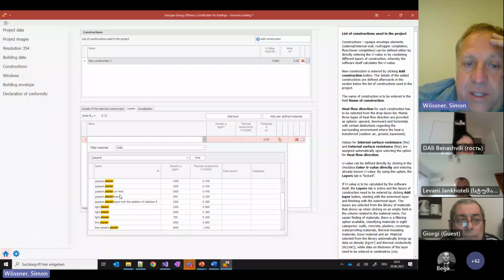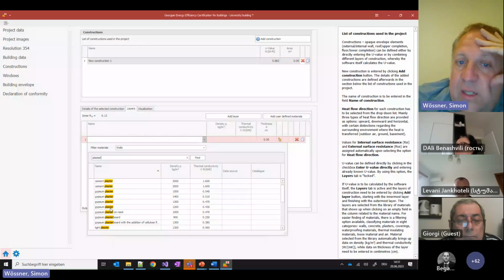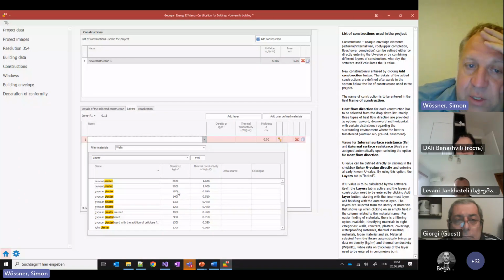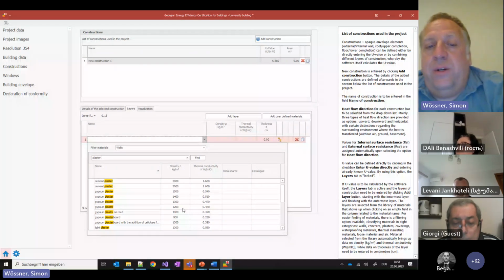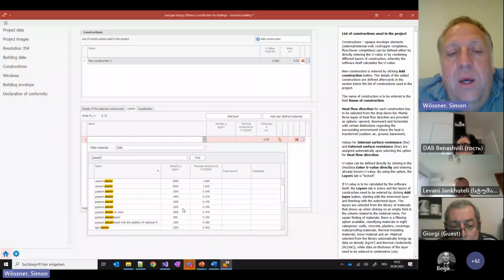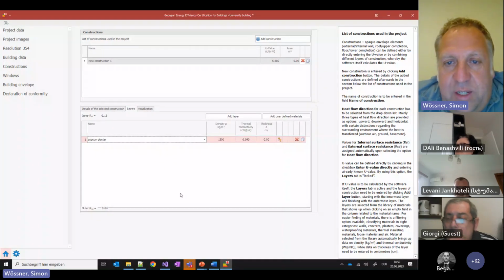then several materials show up, and you might want to ask, why is there more than one gypsum plaster? That is because the materials are there in different densities. So you would either already have the information which gypsum plaster you want to use, or you just pick one. Usually the worst case, to be on the safe side, is what you would do in a preliminary planning.